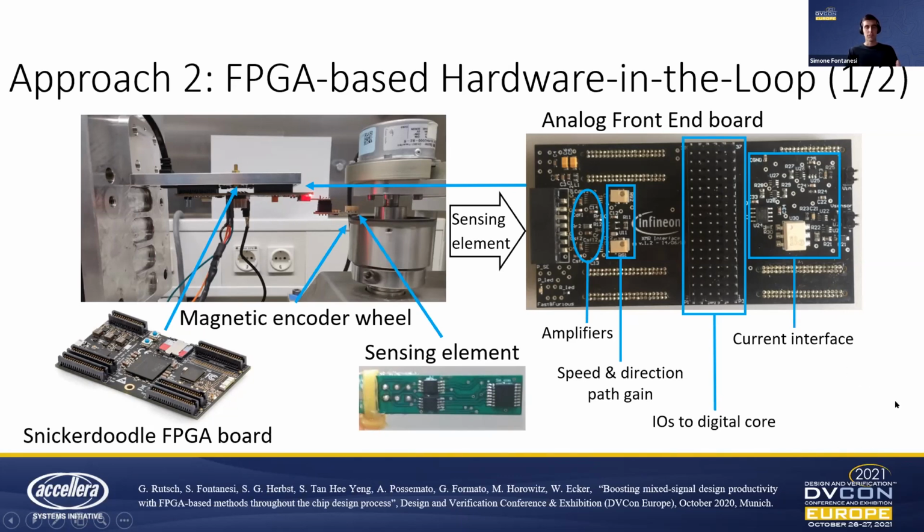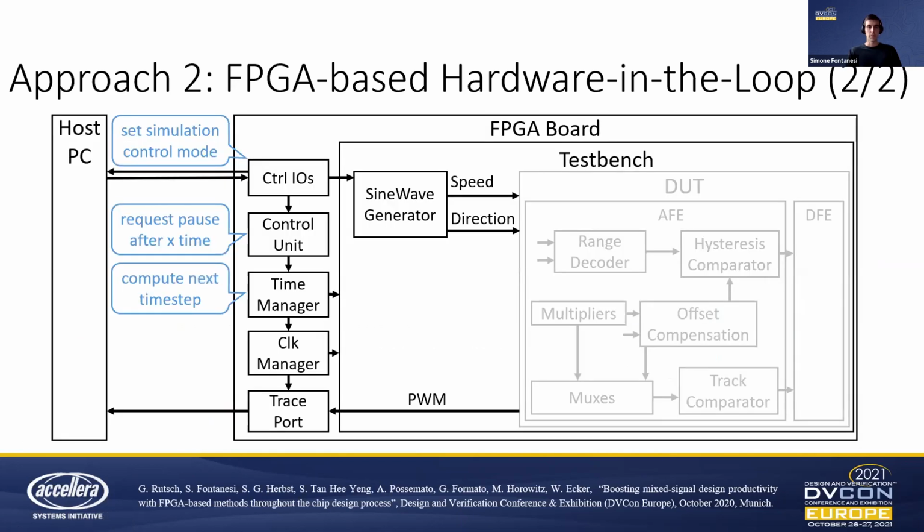And then for this approach, we reused the system on chip in this way. So we implemented everything, from the DUT digital part and the analog front end up to the test bench and the test bench control, inside the FPGA. So in this case, everything was written in a synthesizable manner, including the test bench.